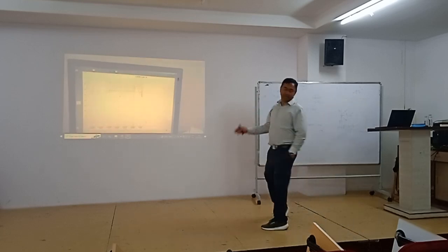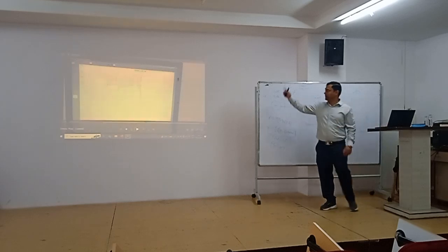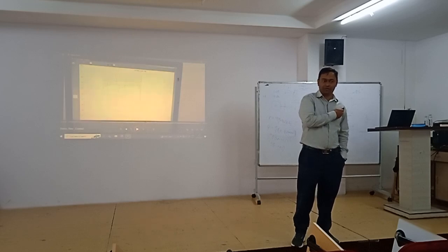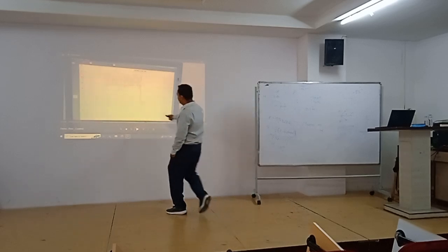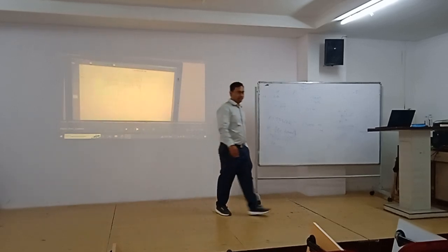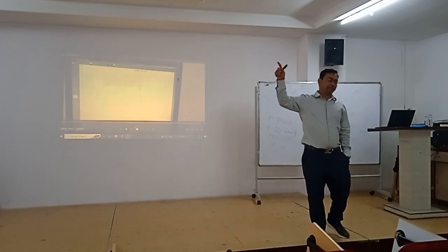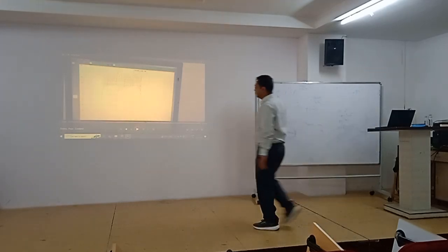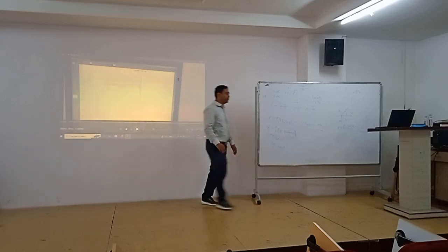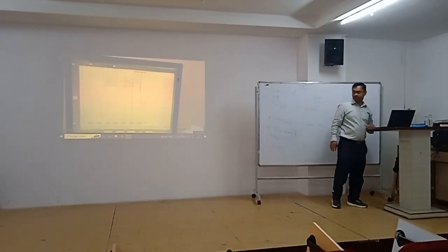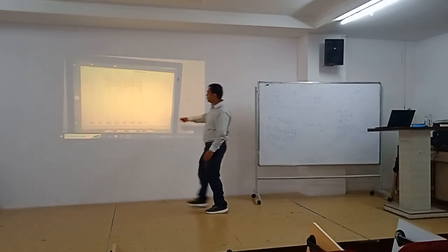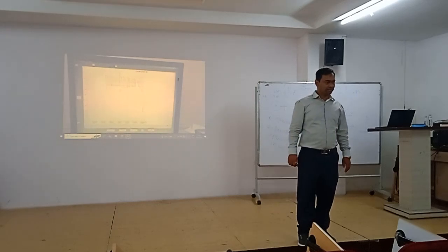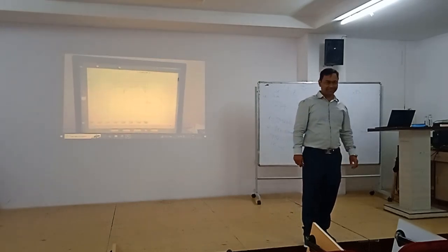So now again we have changed the parameter there and we have done the change in the set point. Yes, that part of the video was not taken unfortunately. So in that we have changed the set value to 50. And we have changed the parameters there also, that KP, KD, KI parameters. If you need, I can explain what we have changed, very clearly. So now it's coming very, very close to it, see. The deviation is very, very small.